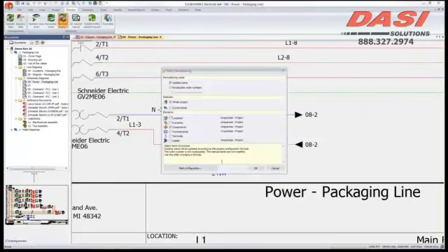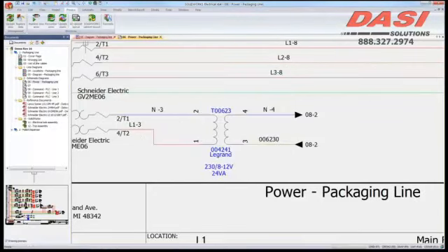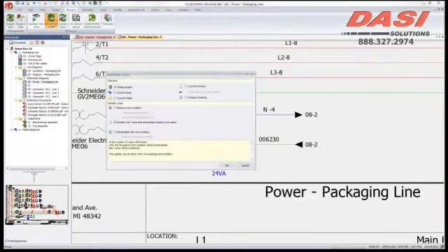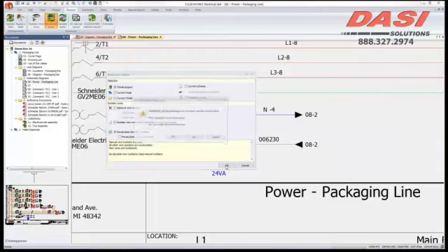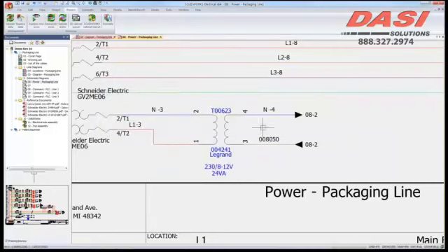I will update the entire set of marks for the project, and sheets 8, 9, and 10 are going to be readjusted, as well as all of the cross-references. Now, I am also going to renumber all of the wires in the project, so that I do not have to go back through and check the numbers. Because I've got this arrow drawn in this direction, it brought in that new number for me.